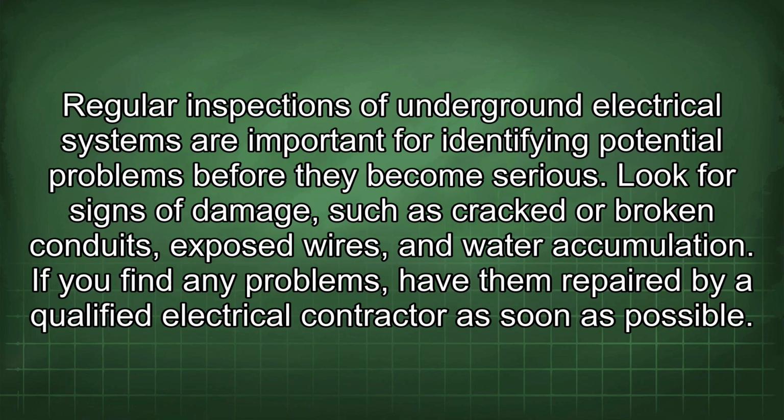Regular inspections of underground electrical systems are important for identifying potential problems before they become serious. Look for signs of damage, such as cracked or broken conduits, exposed wires, and water accumulation. If you find any problems, have them repaired by a qualified electrical contractor as soon as possible.